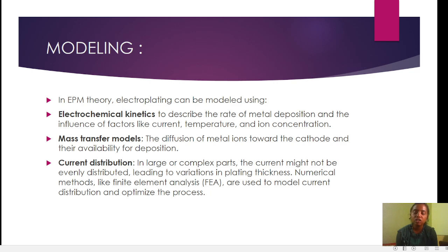Current distribution in larger complex parts might not be even, leading to variation in plating thickness. The current needs to be properly distributed, or else the plating thickness will vary. Numerical methods like finite element analysis are used to model current distribution and optimize the process.